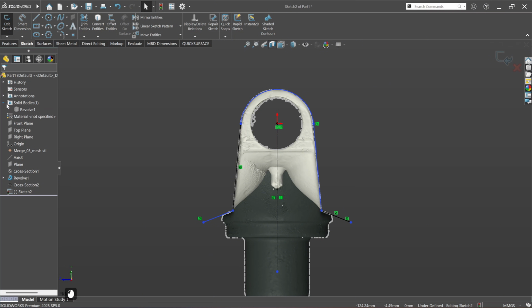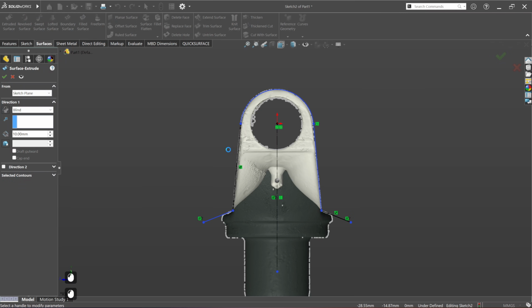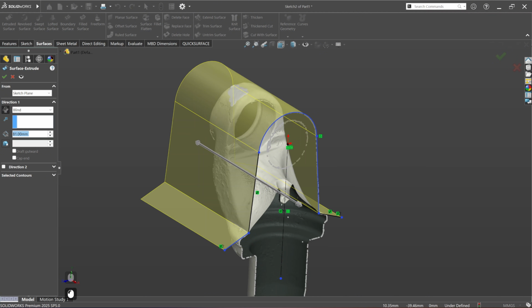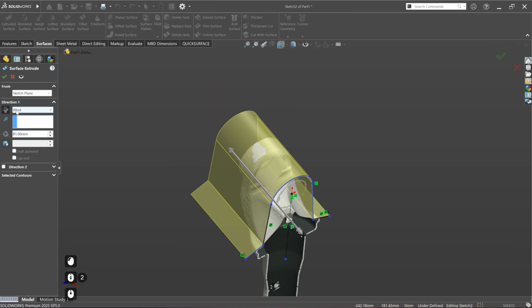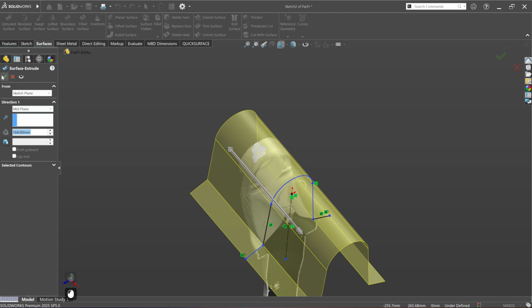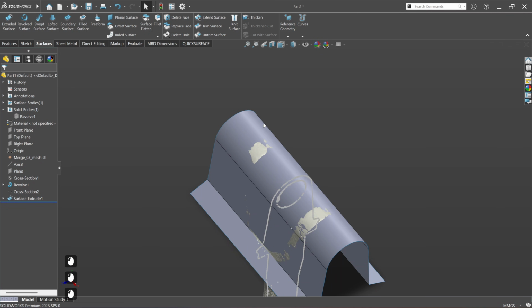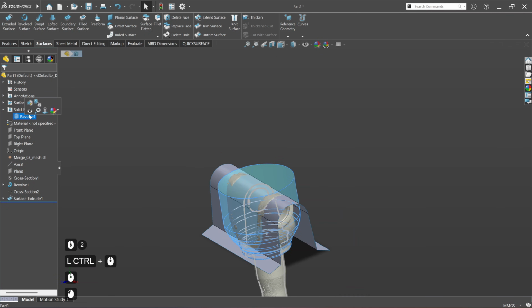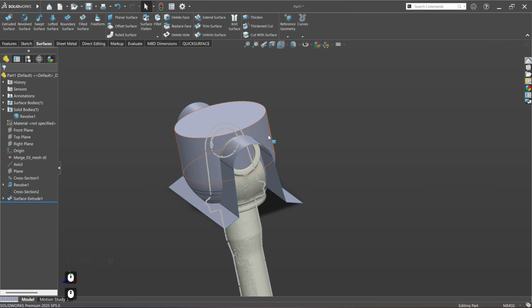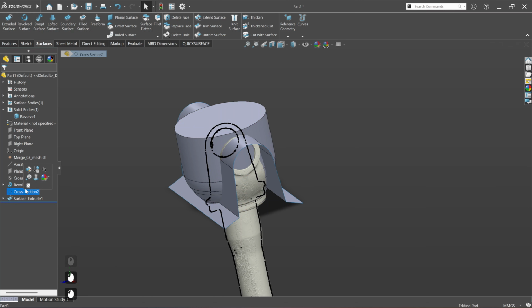Considering SolidWorks tools, we can come over to our Surfaces tab, click on Extrude Surface. So let's make this mid-plane, extending it more than we need. Click OK. Let's get out of our section view and hide our solid. Okay, good. At this point we can again hide our cross section, and in the Surfaces tab we have this